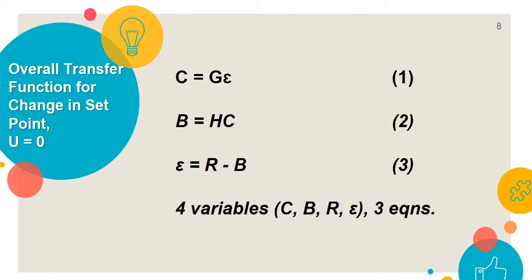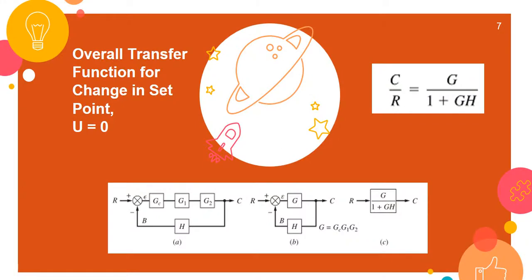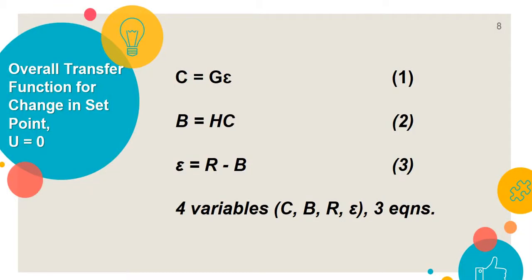The C over the error is equal to the G. Now, where did this particular thing come from? Now, I'd like to go back to this one, the B figure here. The C, the output, divided by the input, which is the error, will bring about the forward loop transfer function G. Okay? So, if the error is cross-multiplied to the G, then that would bring about this equation. C is equal to GE. The E coming from here, and it was just cross-multiplied here.